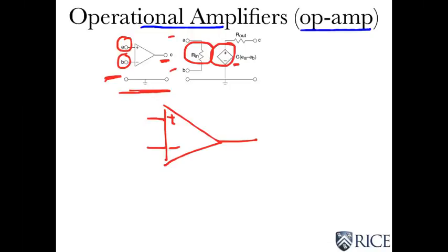And that's why EA corresponds to the plus, and why EB here corresponds to the negative side, because that's how they enter into this formula for the voltage produced by this voltage-dependent voltage source. It's all written in terms of node voltages that are taken with respect to that reference. Finally, there's an output resistor, and this is the output.